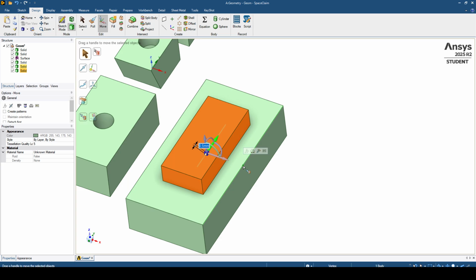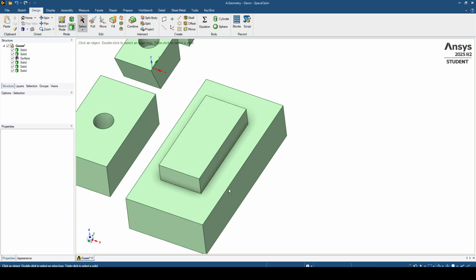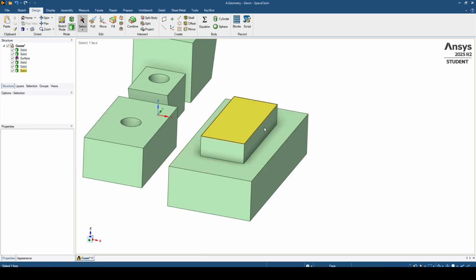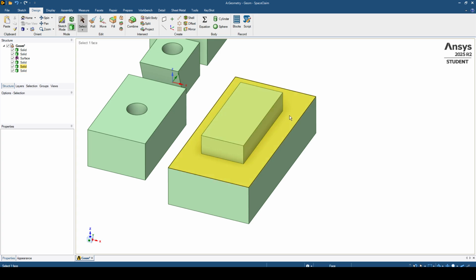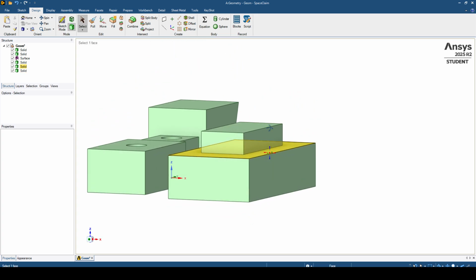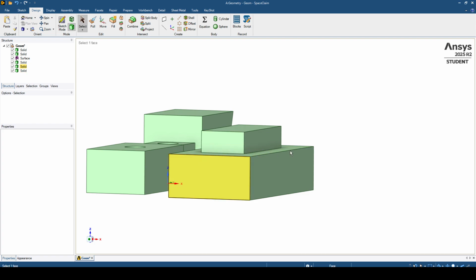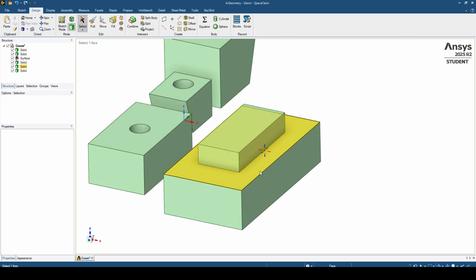I click on it. Now we are on the middle of this side. I click on the other direction and again up to, and moving my mouse along this side until I reach this small form and click on it. Now we can exit. Right now our small rectangle is exactly on the middle top face of this rectangle and touching it on this face.